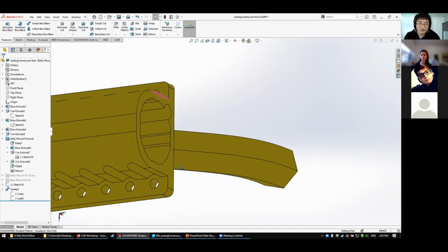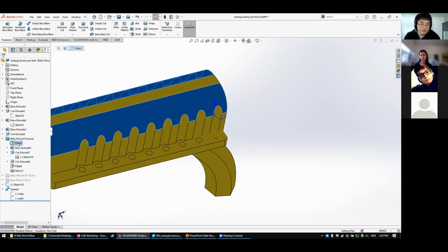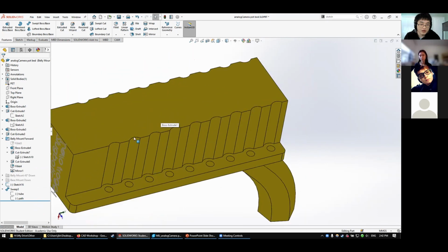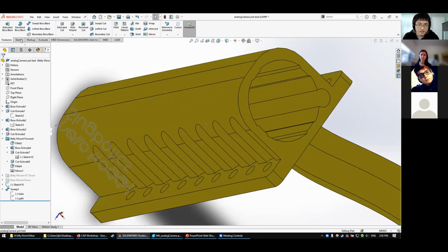So you see here, I have a couple of fillets. Let me see if I can show you this guy. If I suppress this, I think it won't blow up. Yeah, so right now I've got a rectangular prism. If I try to hold this in my hand, hard edges, it's okay, I guess, but you can save some space, save some 3D printing filament, and just make a fillet. And there we go. Pretty nice to do, and it's super easy. Under the Features tab, there is the big fillet button next to the linear pattern.